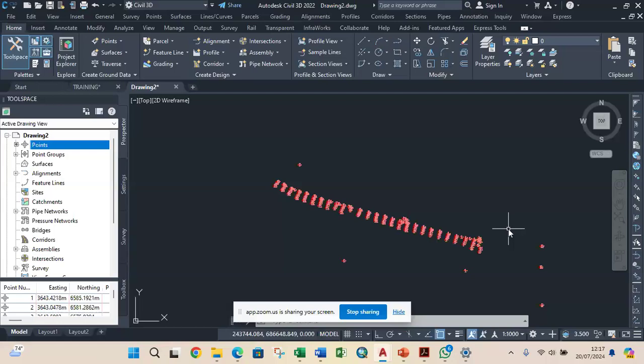It's not just about the width of the road. Many other parameters are determined by this. Then the major traffic, which is also a function of the axle load, also determines the pavement thickness when we come to pavement. Daily traffic shows you the volume of cars that need to be discharged from a route, so that greatly influences the route, and that in turn determines the type of road it is. The type of road is also another factor.